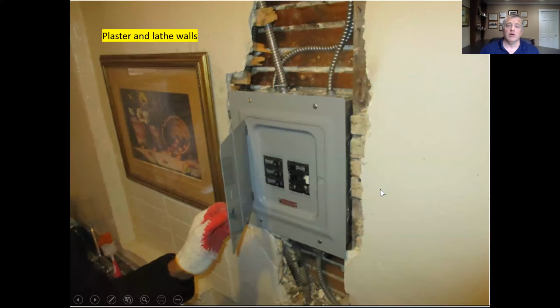Plaster and lath walls. Now, you can kind of see in the top of that electric box what that is. So, post 1960s, we have sheetrock, which is a wonderful material. It's a gypsum-based wallboard that goes up to studs. Before that, they had to build their own walls. So they put up those laths, or pieces of wood, and then what would adhere to that would be the plaster. And then when that would dry after a few coats, you had a smooth finish wall. So that's a very typical characteristic. Actually, it's a guaranteed characteristic of your old tenement buildings.